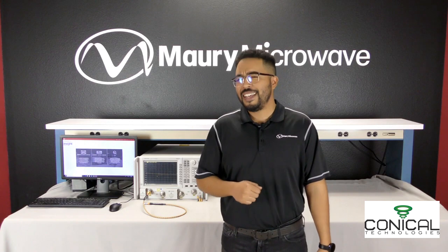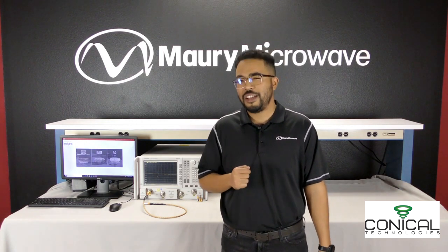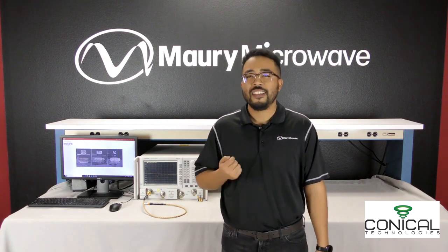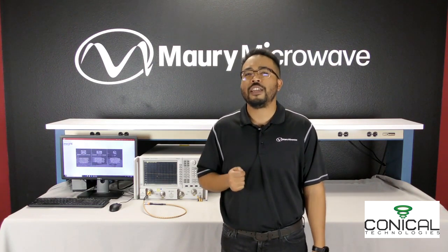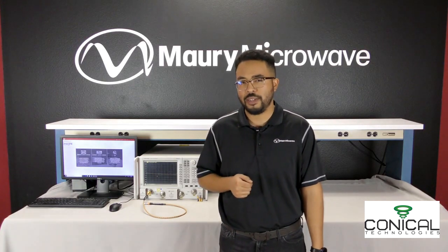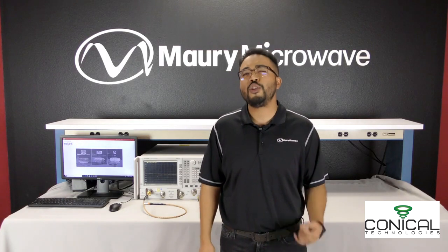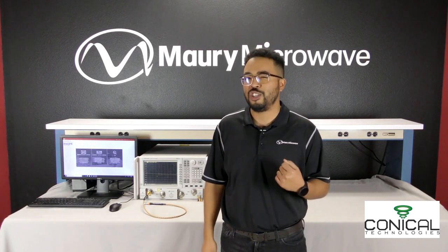Well, that's it. It's that easy. Just characterize the uncertainty of your cables when you first get them, and as you saw, it only takes a few minutes. The next step would be to recharacterize the uncertainty at regular intervals and replace the cable proactively once it no longer meets your expectations. This way, you will prevent the negative impact which comes from using degraded cables and making bad decisions based on unreliable measurement data.